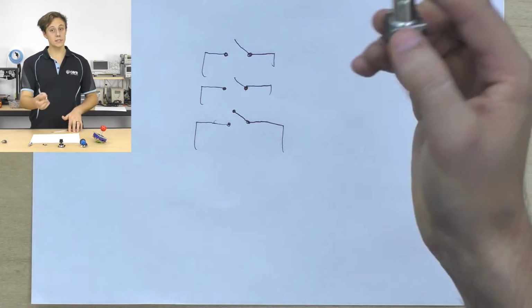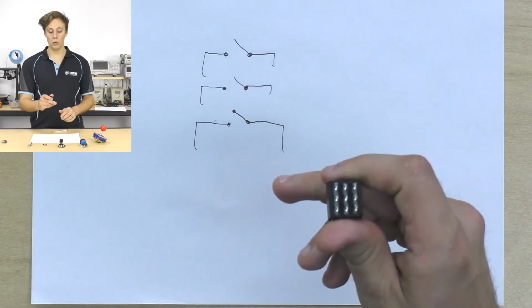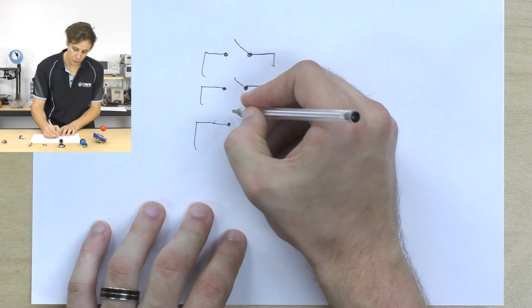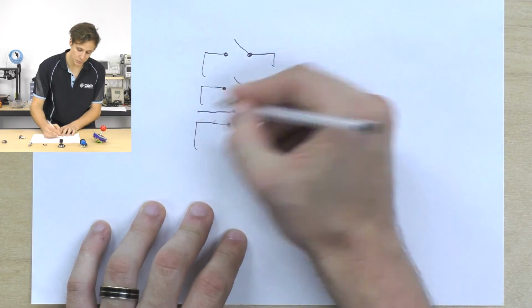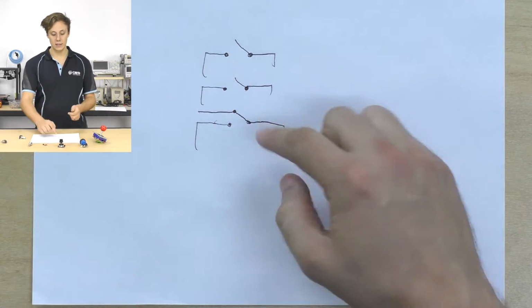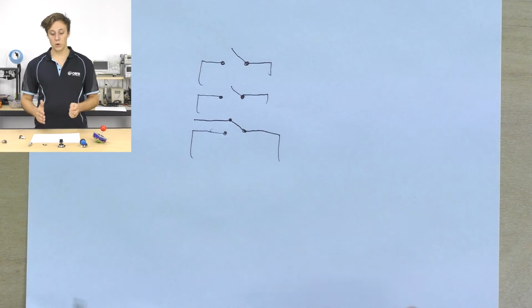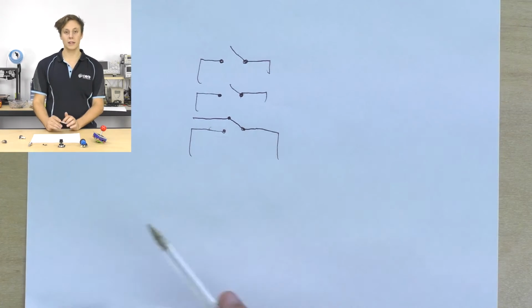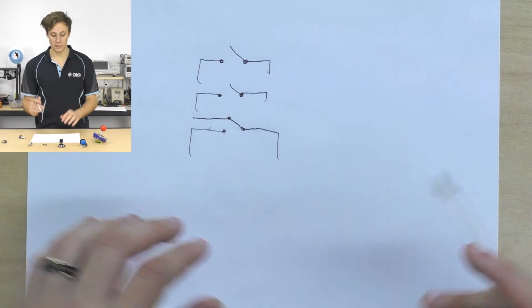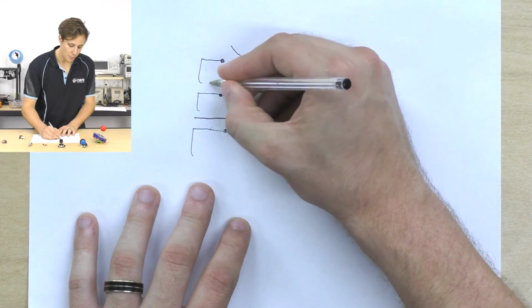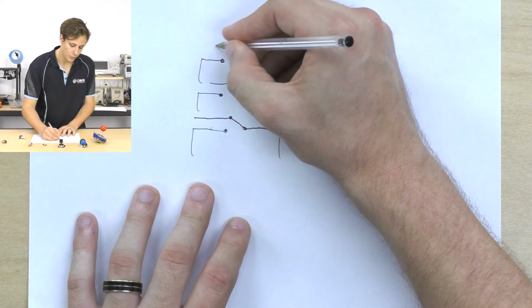I'll use this as another example. This is a triple pole double throw switch. With a single pole, single throw switch, when it's disconnected, it's connected to nothing. There's no physical contact. There's only two contacts on it. When it's closed, they're connected. When it's open, not connected. But a double throw switch actually has another pin connected to there.